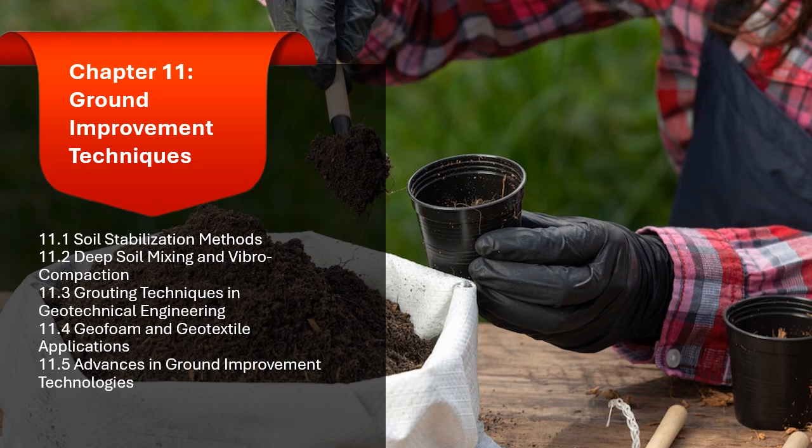1.3.3.2 Groundwater control and seepage prevention. Grouting is often employed in areas with high groundwater levels or water-sensitive soils. It is used to prevent water seepage into excavations, tunnels, or basements, and to create impermeable barriers in dams, levees, or tunnels. Chemical grouting and permeation grouting are commonly used to reduce permeability and control groundwater flow.